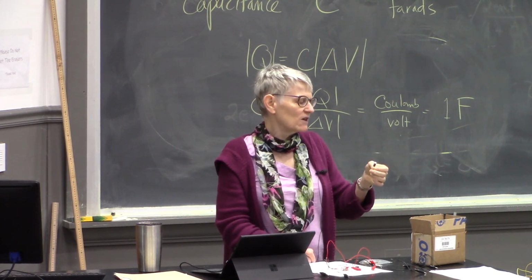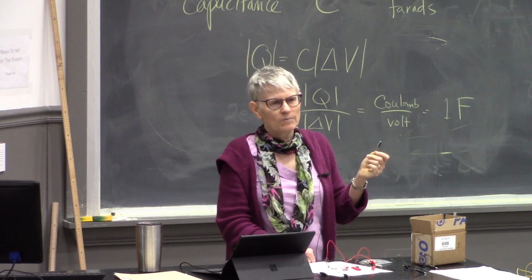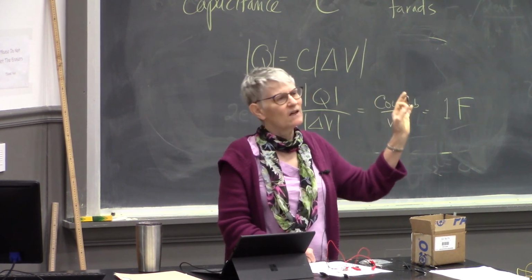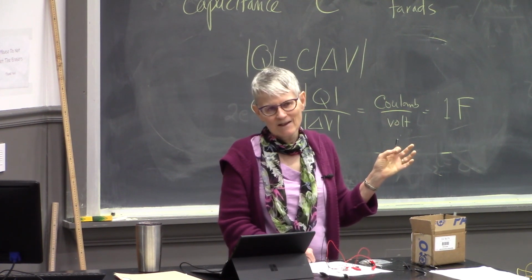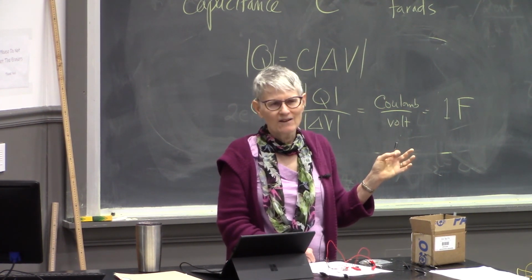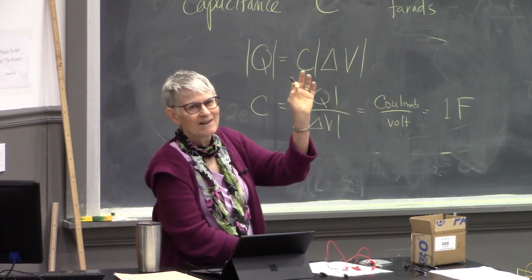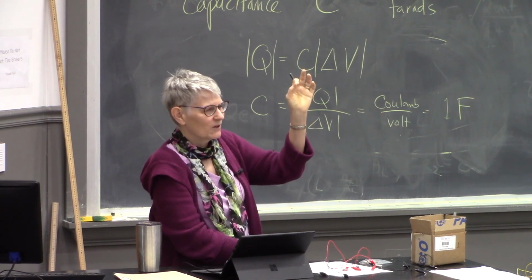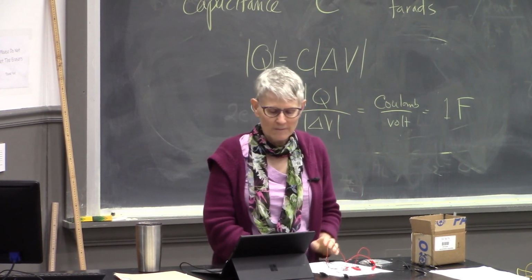This capacitor says it's 1 farad, and it also says 2.5 volts, which suggests that's the maximum potential difference you want across the capacitor. Now we're putting 3, and that's okay. I wouldn't do 6. I wouldn't even do 4.5. But 3 is reasonable for the ones we're using here.